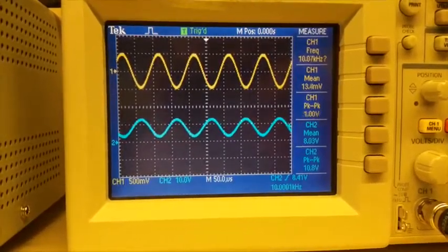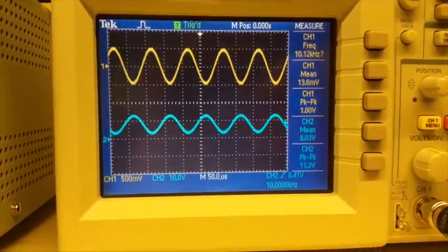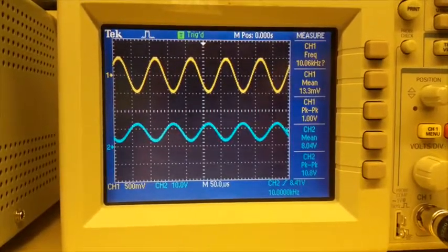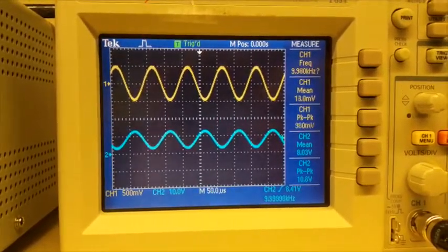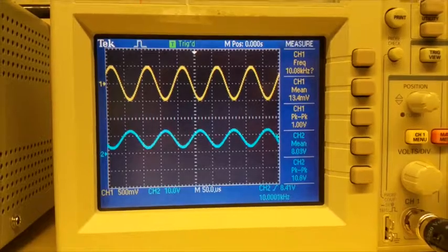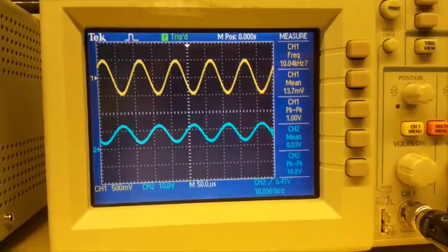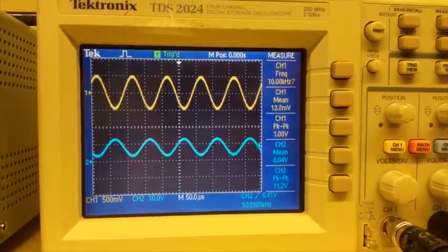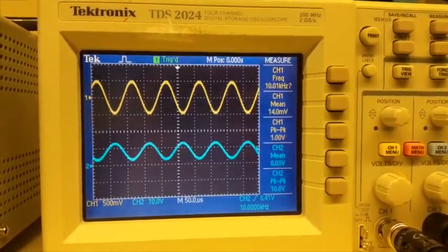My signals for VN and VC. As you can see, VC is 180 degrees out of phase with VN because the transistor acts as a switch, so when there's a positive signal, the switch is open and VC potential is negative, and when there's a negative signal, the switch is closed and VC potential is positive.